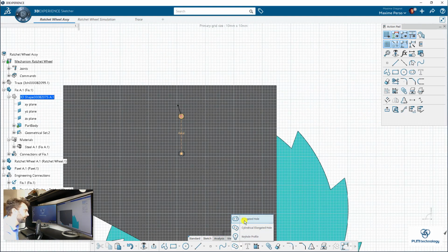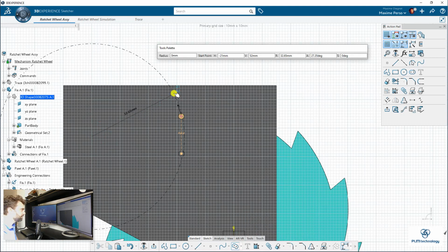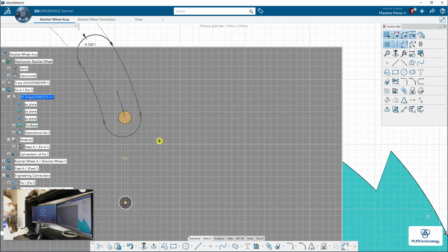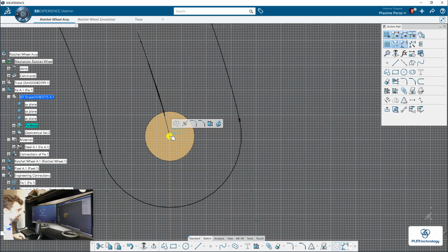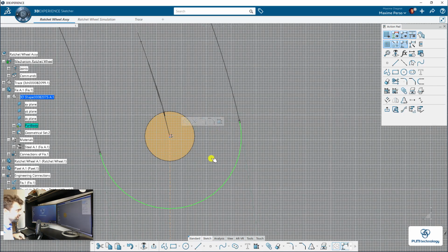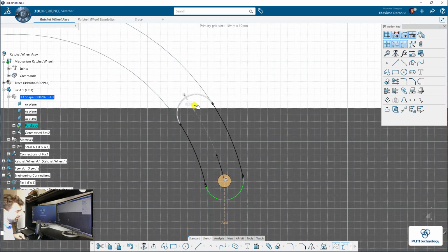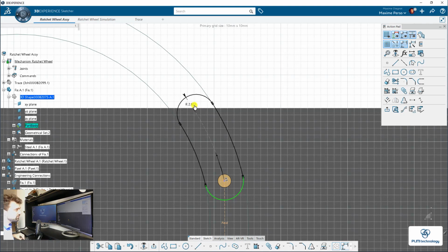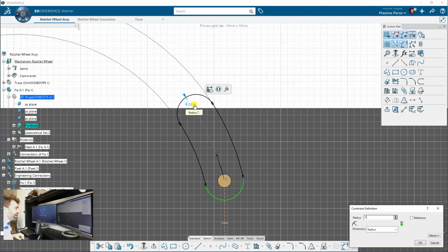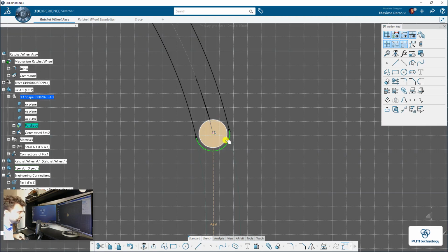And as you can see here, you have a nice feature called cylindrical elongated hole, and we will select this one. And you see you are going to make a diameter with that. So clearly it's a bit big now, and obviously something is a bit sketchy here. I will not use parameter in that case. I will use the fix option here. So, well, this is not perfect because this design is not parametric. But in that case here, it's working pretty well because we are using the traces, so it will be hard to get something parametric anyway. Another thing, the radius of my pin is about 1 millimeter, so I will put 1.2. Okay, we have a bit of tolerance in that way.